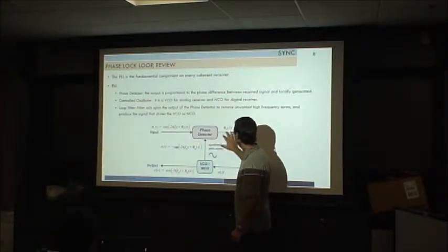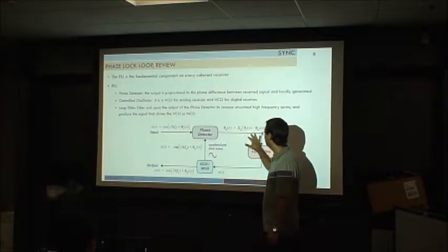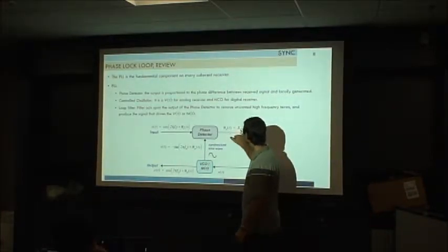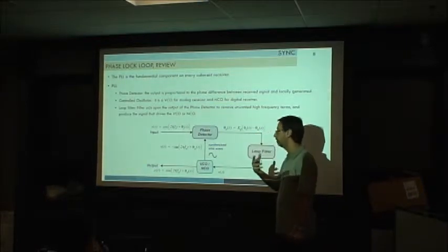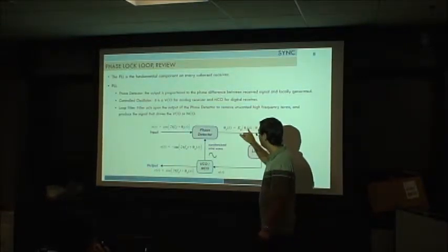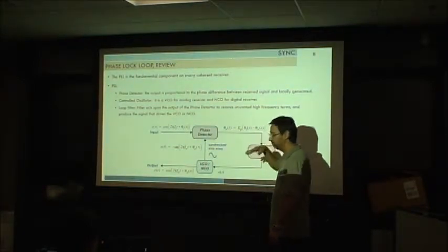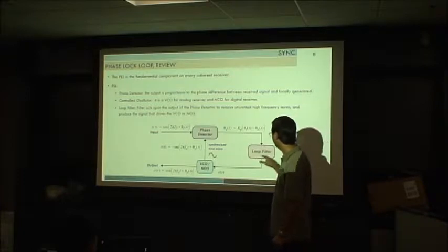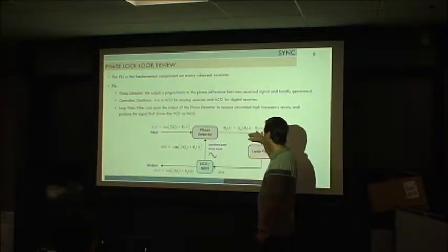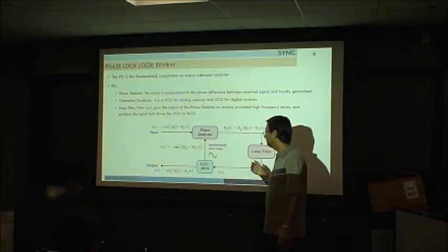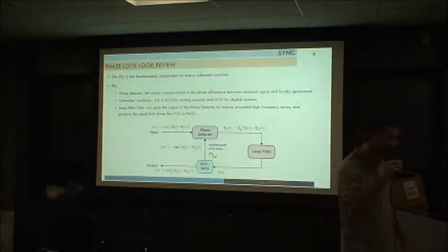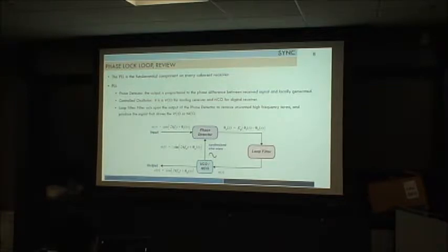And this phase detector, at the end, we will get something like this, something proportional to the phase difference. That is what we want, to see what the phase difference is between the two signals. And then filter that, because here will be some high pass filter. Sorry, this is a low pass filter, that will filter some high-frequency components, and well, this is how this works. But we want to start looking in detail at each of the blocks.